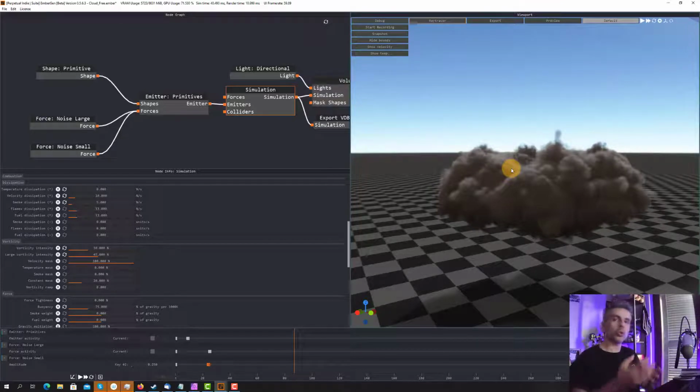So we are going to have a higher resolution. We are going to break, as you see, the cloud surface, so it will be less smooth and we'll have more turbulence, more perturbance, and it is a really nice way. Actually, the vorticity is based on masking, so there are values and parameters that are controlling how the vorticity is applied. We have 100% based on velocity, and we are going to take care of it, but I like to add something else. So I like to decide that there are other values and other parameters that are controlling the vorticity.